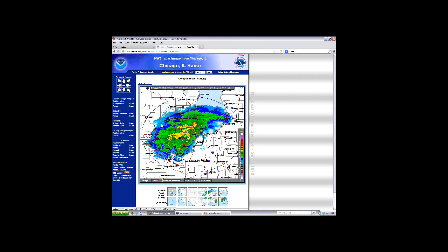Once you have a dual polarization radar with two receivers, of course, one is doing H and one is doing V. If temperature effects, for example, cause the gain of one receiver to change relative to another, that begins to bias the ZDR measurements. And similarly, the phase between H and V, the sort of basic system phase, can change due to operating temperature and so forth.